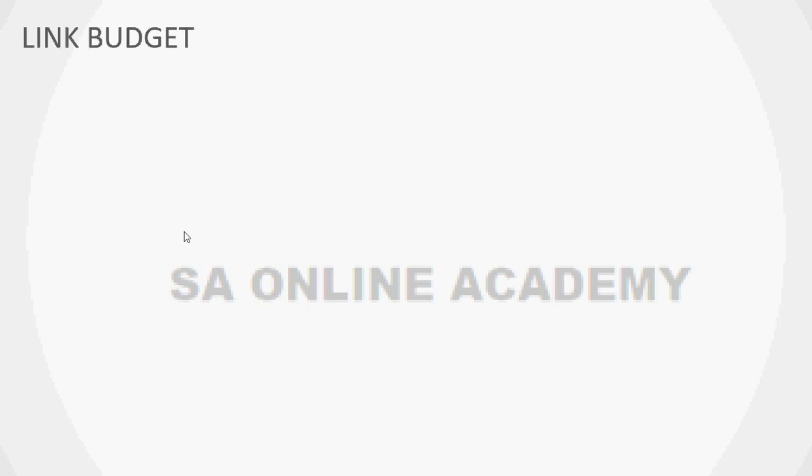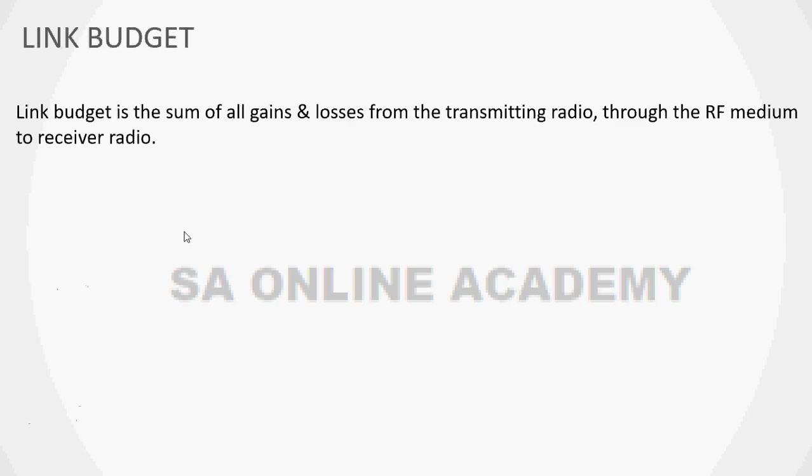Link budget is the calculation of all the gains and losses from transmitter to receiver. From the transmitter, the signal goes through the connecting cable or connectors, then to the antenna, then the receiver antenna passes it through the connecting cable to the receiver. There are a lot of losses in between, and a lot of amplifications in between. The calculation of all these losses and gains through a path is called link budget. So link budget is the sum of all gains and losses from the transmitting radio through the RF medium to the receiver radio.